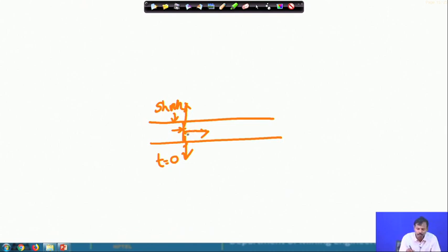So, the shock is travelling in all directions from the explosive, and as it moves through the explosive column, the explosive is being disintegrated and the shocks are being released in all directions. But if you consider this position at t equal to 0, shock is released, the explosive chemical is disintegrated into a number of elements, but those elements have not rejoined to form the gas.